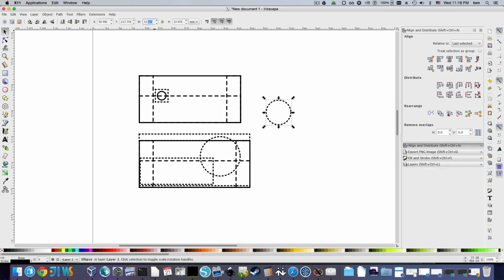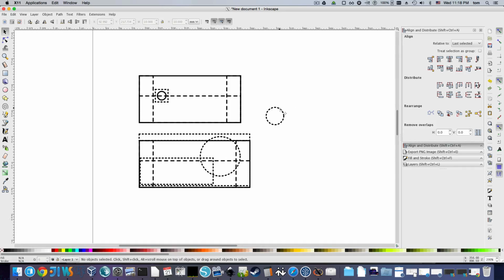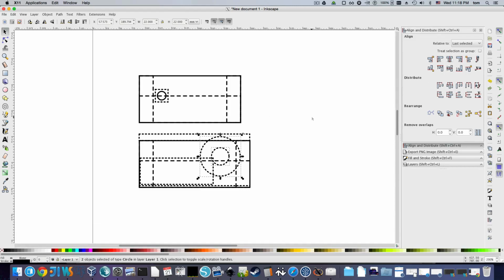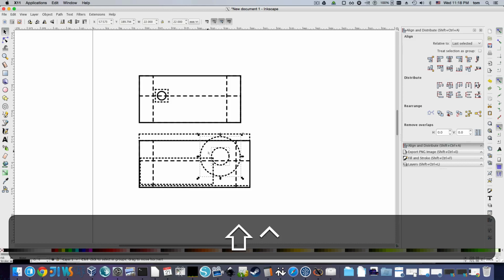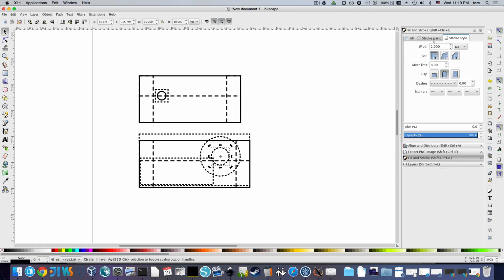So draw another circle to represent that, and we'll align that to the center of this one. And you can see this is where it starts to get tight. I'm going to group that together, but I'm going to make this one solid because we're going to end up drilling this out later.